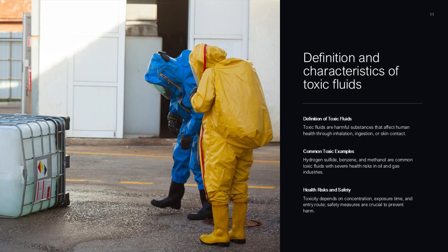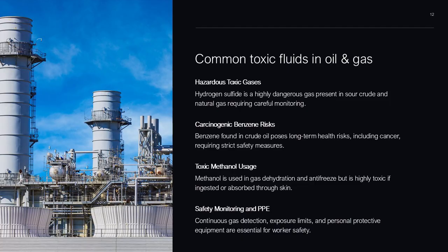H2S is particularly dangerous because it is highly toxic and can be fatal even at low concentrations. Benzene is a known carcinogen, and methanol can cause blindness or death if ingested. Proper identification, monitoring, and protective measures are essential to prevent exposure and ensure worker safety. Hydrogen sulfide or H2S is one of the most hazardous toxic gases encountered in oil and gas operations, often present in sour crude and natural gas.